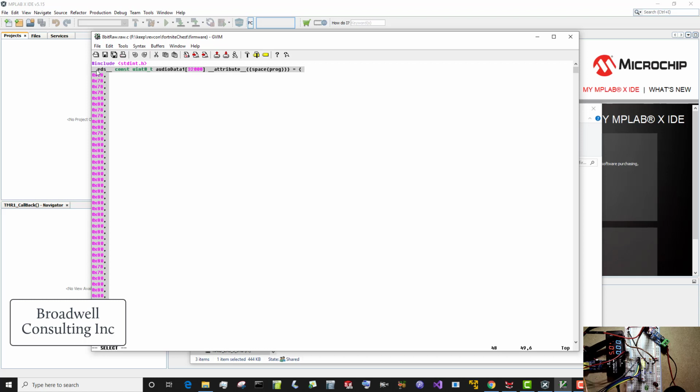We're going to be using the XC16 compiler for Microchip. It has a couple of limitations. First, it doesn't allow arrays longer than 32,767. So we took our array and broke it into two separate parts, and we'll handle the switching between the two arrays in software. Also, since there's not 32 or 64K worth of RAM, we said store this data in the program space.